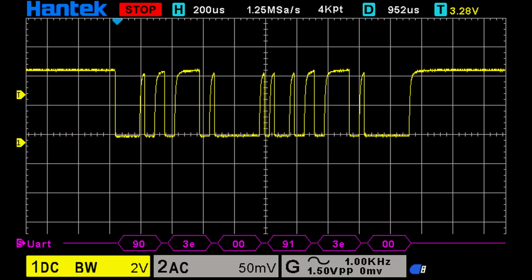Now I'll release the key. Here the commands are the same, except the note is turned off by using a velocity of 0. Another way of turning the note off is to use a starting nibble of 8 instead of 9. In this case, the first byte of each MIDI event would be 8-0 or 8-1.